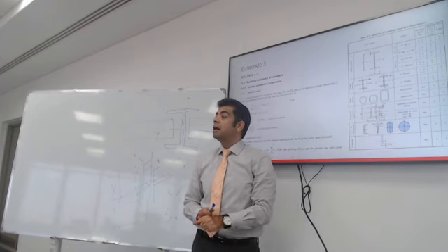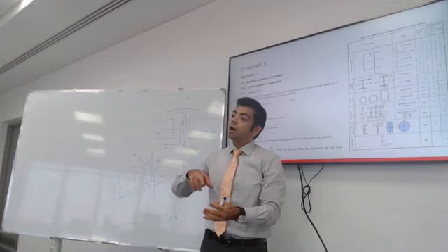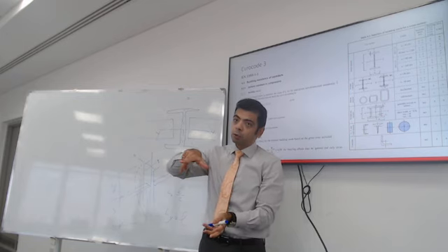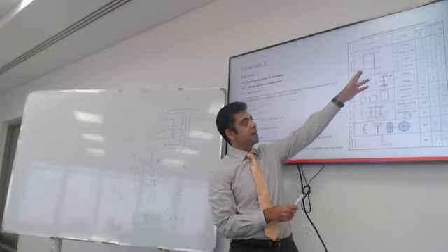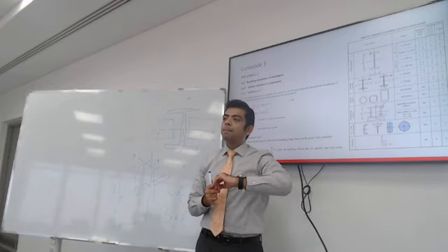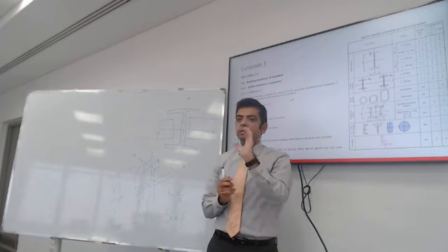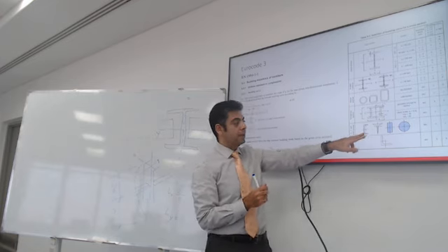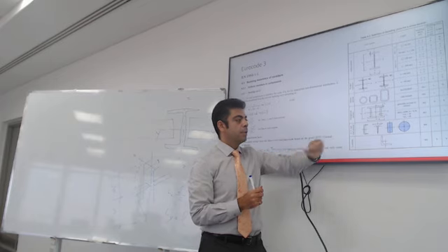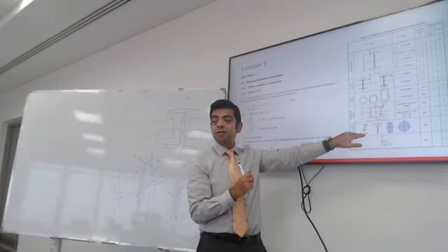They're very effective because they don't have lateral torsional buckling. They don't buckle as easily. Open sections like these, you need to check them more closely. Open webs like these, you will have further reductions in the capacity.